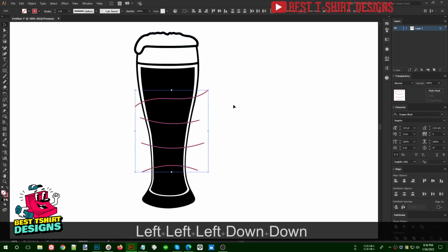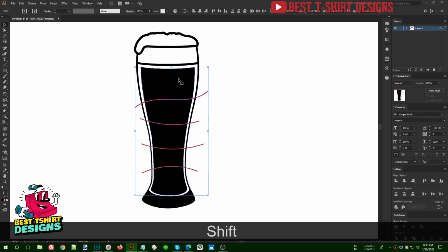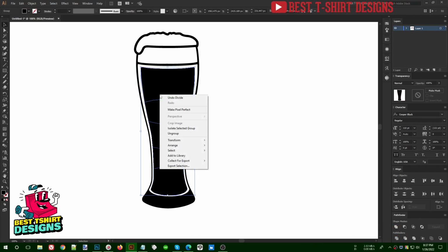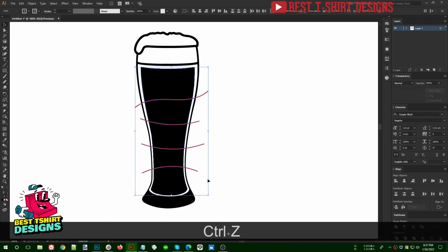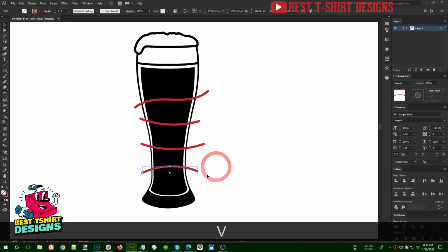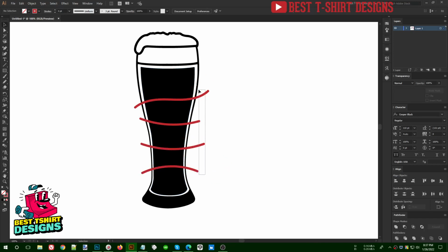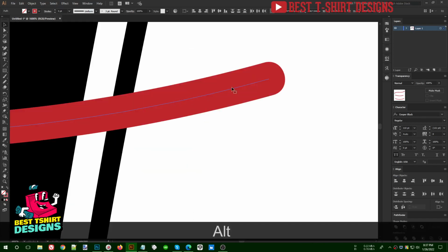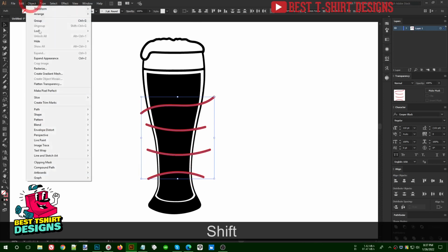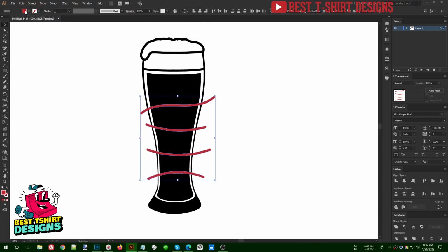in this position. So once it is done, select this shape also, and then click on this Divide option, that is going to divide my shapes. And once it is done, click on Ungroup. Or before doing this, we can do one more thing, that is, this is a stroke. So if we need some gaps between the shapes, we can increase the stroke size. But the problem is, if it is a stroke, then the stroke size will not matter. It will only matter the thin blue line you can see between the stroke. So we need to expand it first of all. So go to Object, Expand Appearance, and as you can see now it becomes fill color.